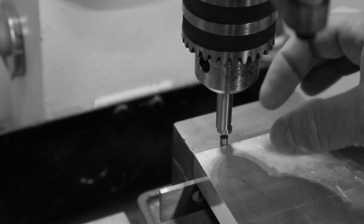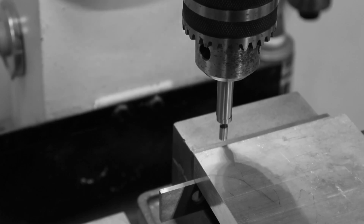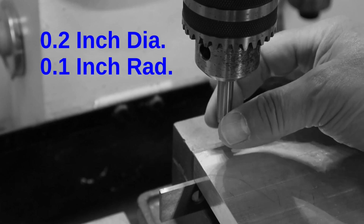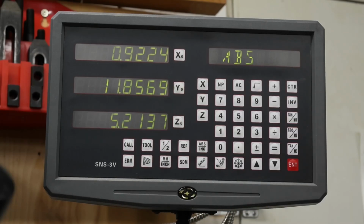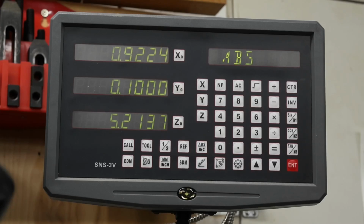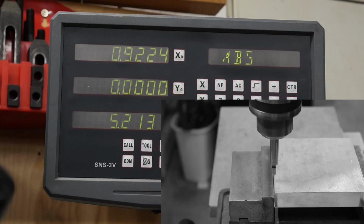Now at this point, I am half the diameter of this tip away from center line. So I need to come over the radius of this diameter, which happens to be 0.1 inches. The axis I was moving was the y-axis. I'm on the far side of the piece, which would be y of plus 0.1. So I could preset it to y 0.1, enter. And then I could jog the table over to 0, and that would bring the edge finder into perfect alignment with that back edge of the workpiece.